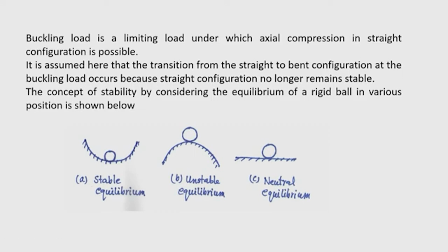You can see in steel structures, whether it is a column, suppose a column may consist of a box section where the sides of the box are plates. So, in that case the plates will buckle according to the manner in which plate buckling takes place.